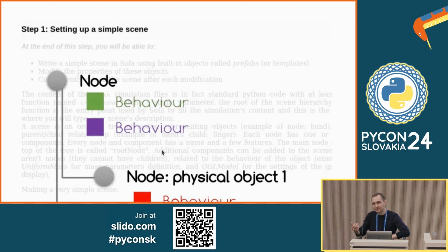A scene is nothing more than a kinematic tree, as you might know from other areas. It's a tree of nodes, and each node has some behavior. For example, this room is a node, a root node, and inside of the room there are people around. Each of us is a separate node that's a child of the room, and we all have properties. We have our own weight, our mass. We sit on the chairs, so the chairs are nodes too. There is a force happening so that we don't fall through the chair, which is a collision, a force happening on both sides.